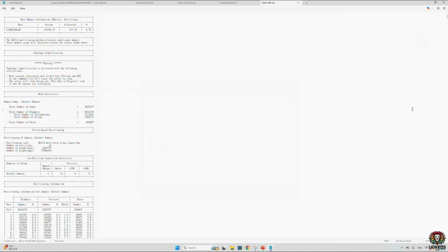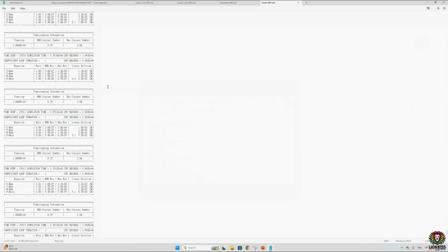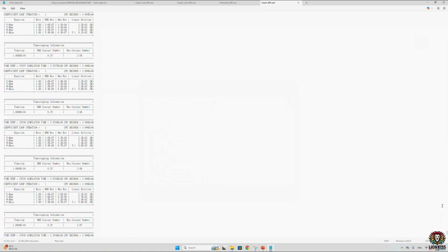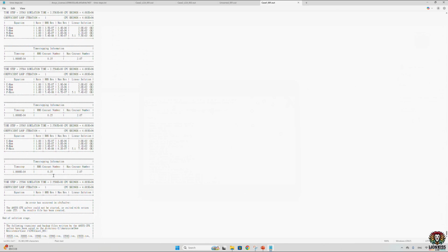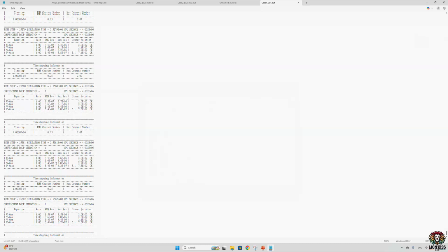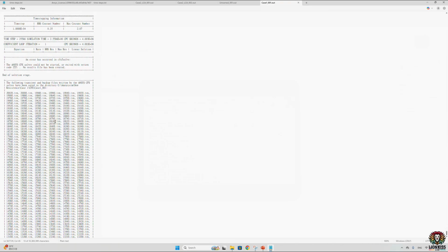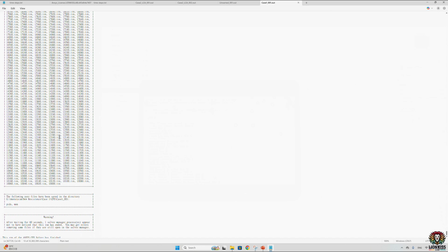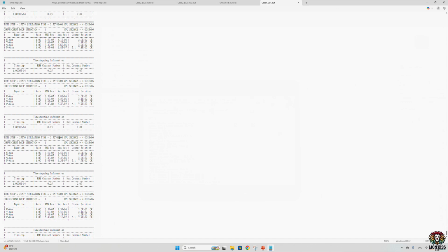number of faces. And if you go down, you can see the simulation time and Courant number also. Like our Courant number is 0.2 here. Yeah, Courant number is at 0.2. So you can see all the details of your simulation, in which Courant number, Reynolds number, simulation time, everything you can see here. Okay, we need to close it and go for the post processing.